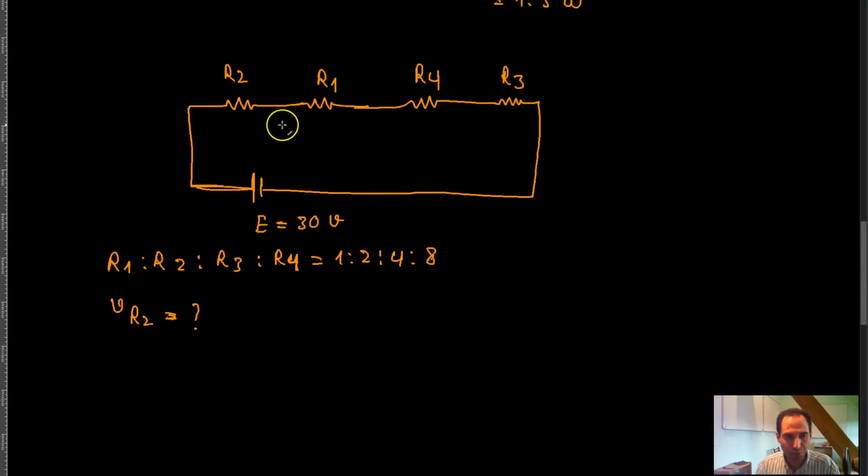So in this particular case, you want to calculate the voltage drop across R2, right? So to calculate the voltage drop across R2, you have to apply Ohm's law to R2, or you essentially have to write V of R2 is equal to R2 over R of T times V of S. V of S being E here, basically the power supply.